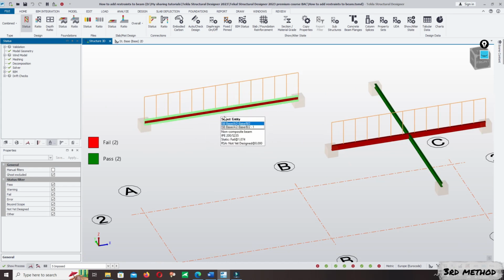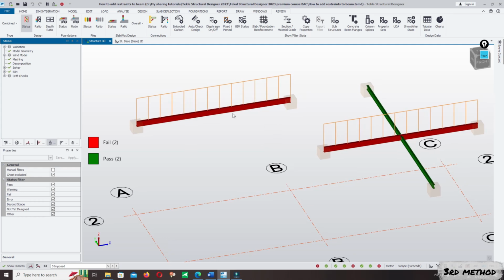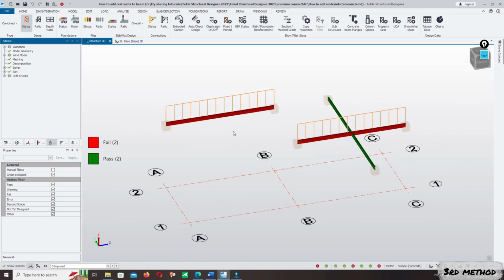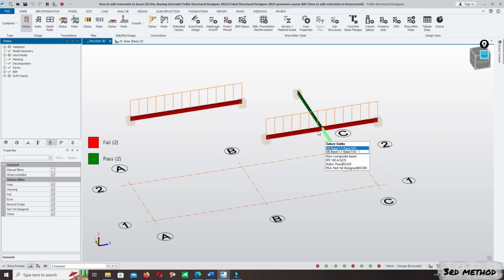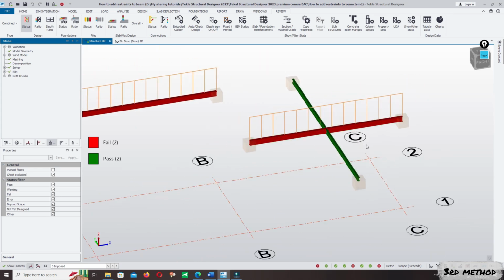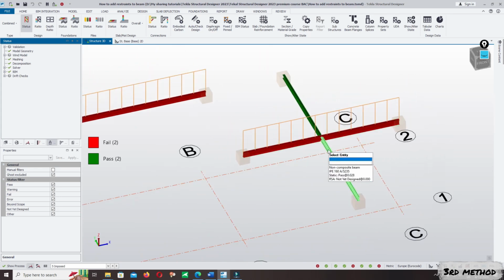We apply only the factor without adding other load from the sub beam. The concept is the same when you apply the factor during modeling, and when you apply the sub beam to correct the lateral torsional restraint.